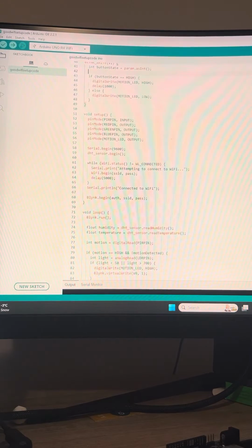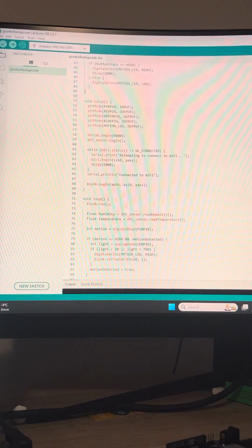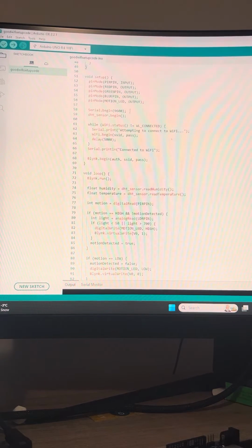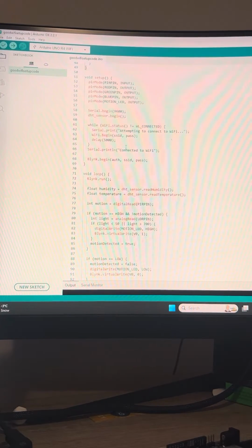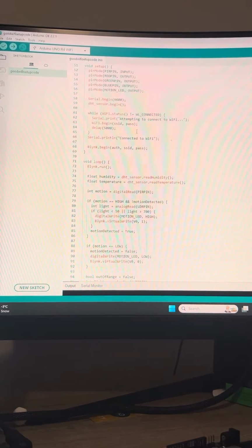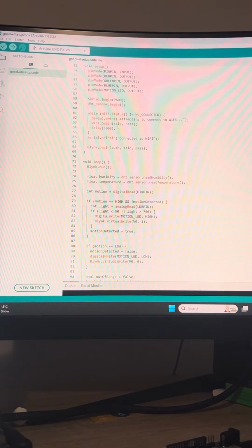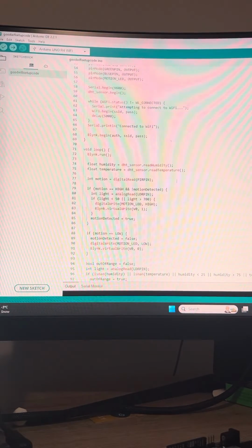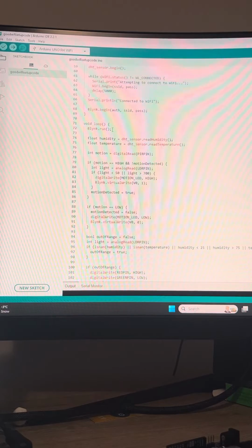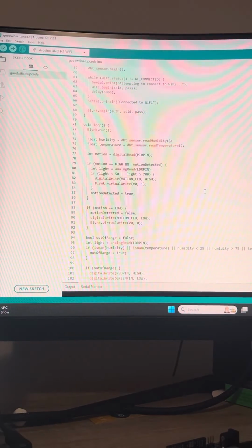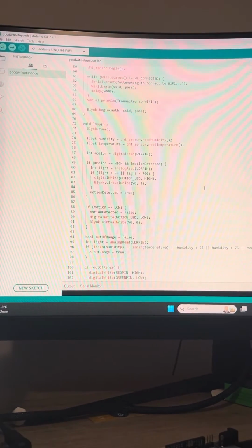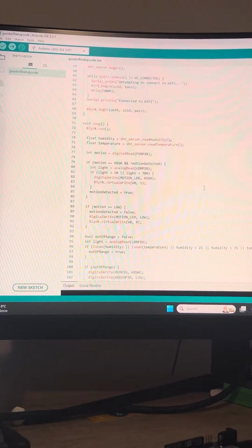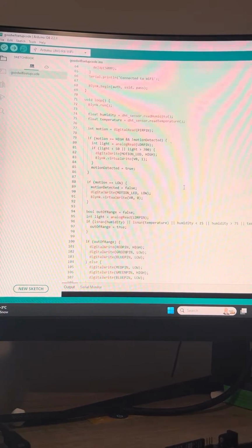So then for our setup loop, we get to set up the inputs and outputs here, and then we set our data cycle Wi-Fi connection. It checks to make sure that the Wi-Fi is connected. Once that happens, you can then connect to your phone. So this all runs before any of this starts to happen. So then the Blink runs. So then that activates the Blinks app in your phone and starts the transfer of data both ways.